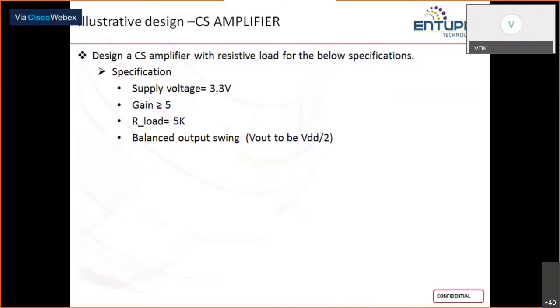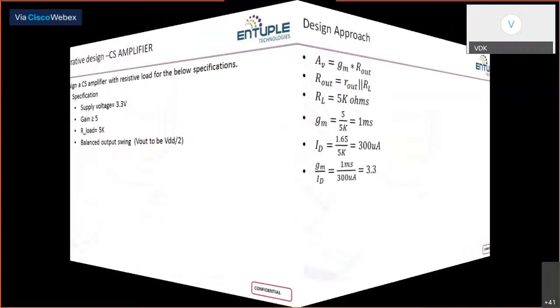That means, if you look at the gm curve, gm is almost hitting its maximum value. However, strong inversion also means that I'll be operating at a large value of Vg. That means my overdrive voltage is also large, and therefore the voltage swing available across that will be small.